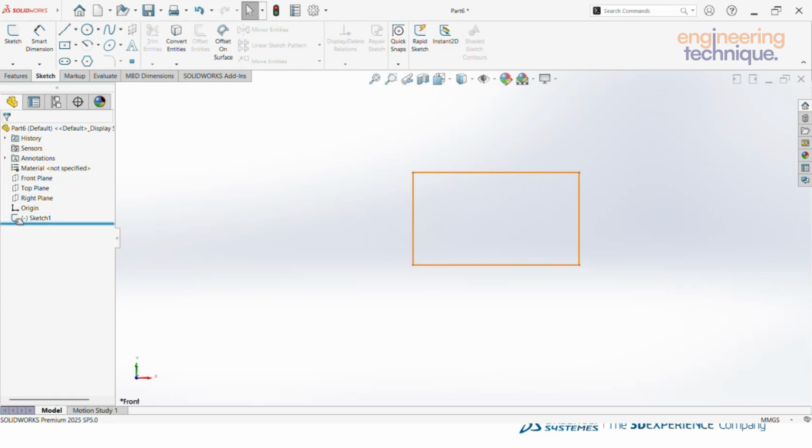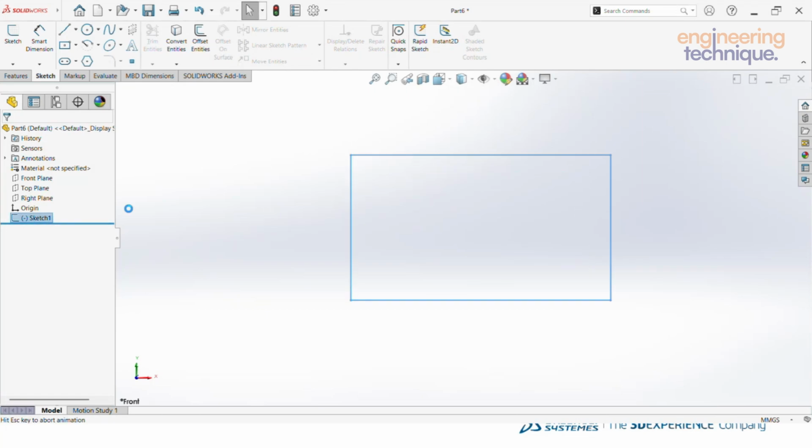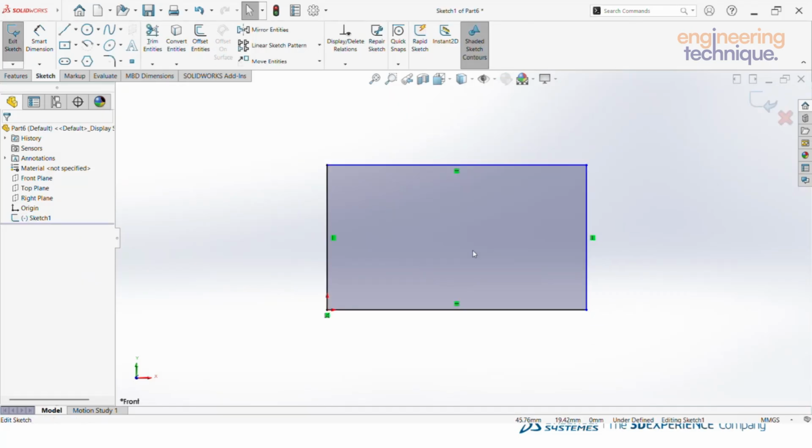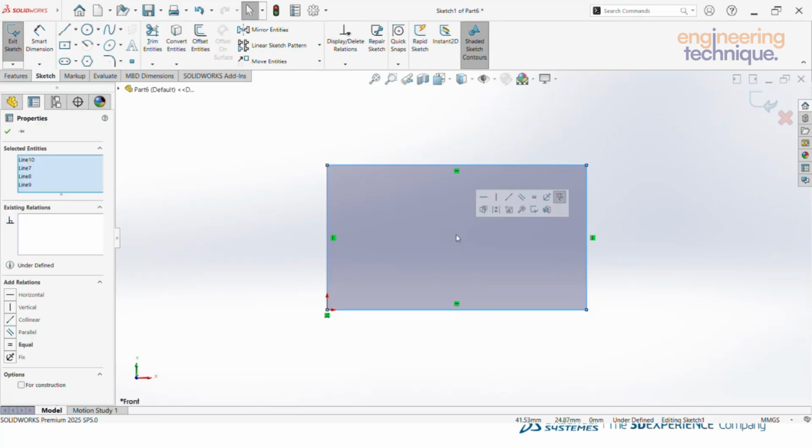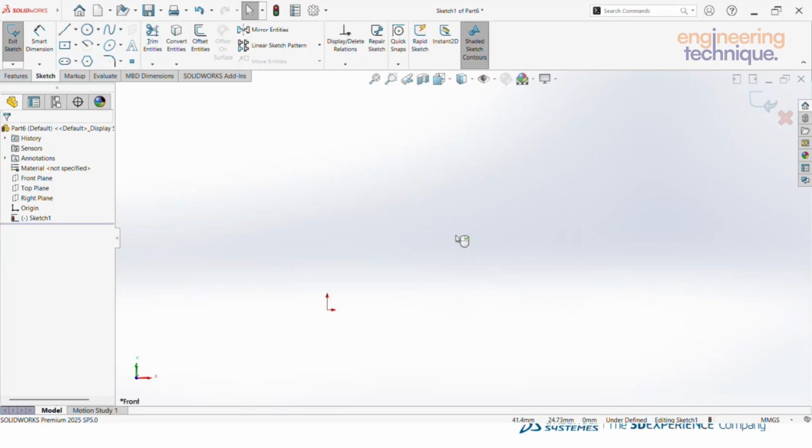Right now you can see that the sketch is properly rebuilt, and it has fetched the geometry which I created last, and the rebuild option is gone, and it is properly updated as per my last option selected. Okay, so after that, I just delete it again, and it shows the rebuild option again. So we can opt for the rebuild with Control Q.